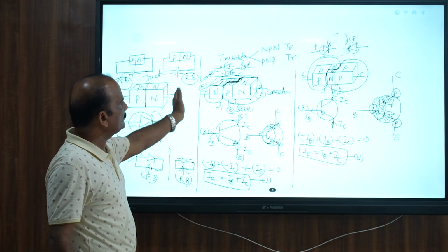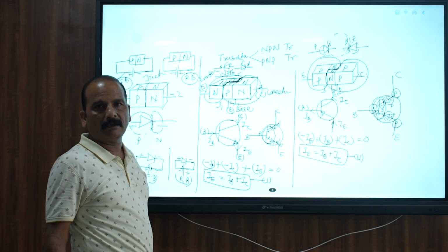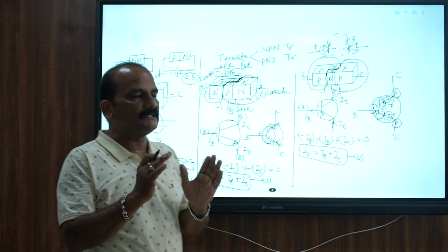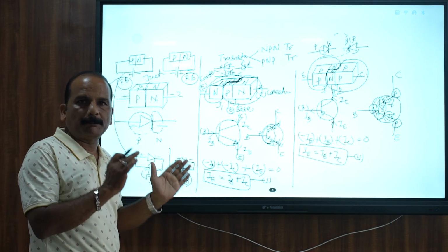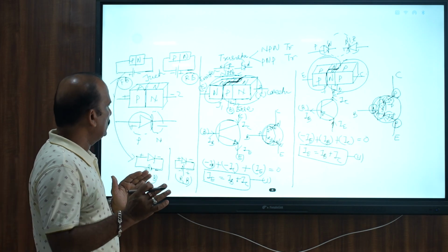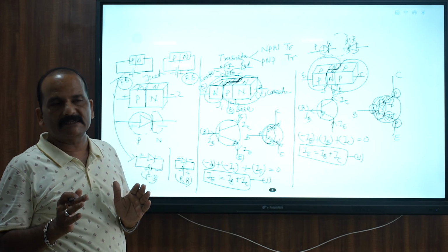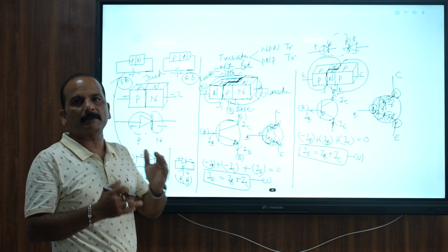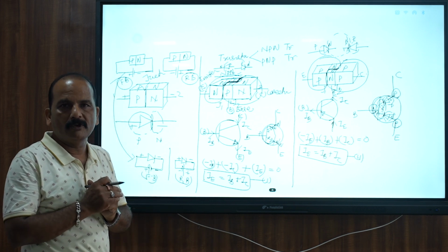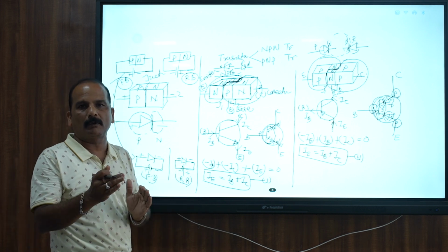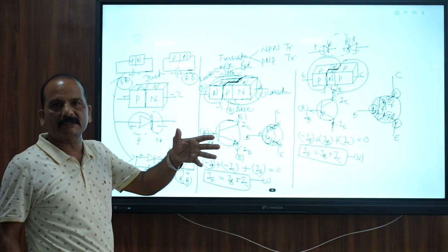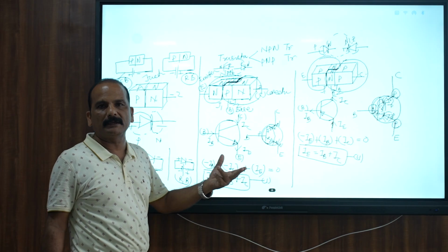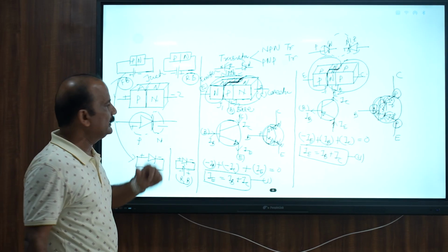So anyway, this is the connection diagram of this transistor. Now we shall discuss its working, how junction 1 and junction 2, one is forward biased, another is reverse biased. Forward biased is providing low resistance and reverse bias is providing high resistance, for which the transfer resistance situation occurs, so that a signal jumps from input to output with a high voltage, and the voltage drop across the output through the low resistance RL becomes high, so that the transistor becomes used as an amplifier.